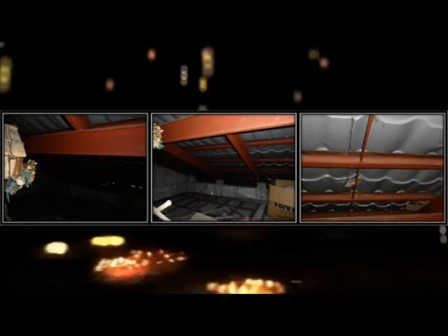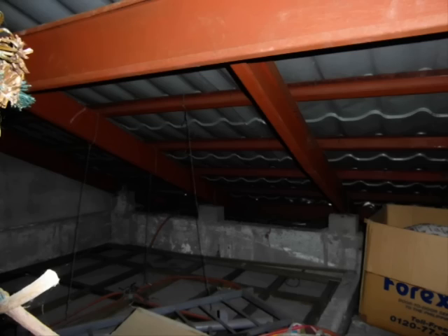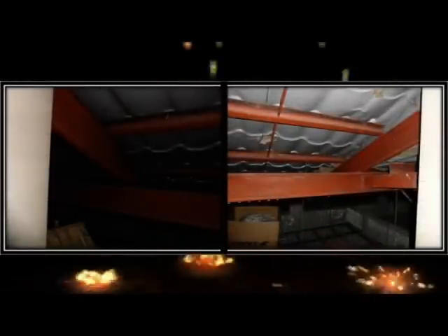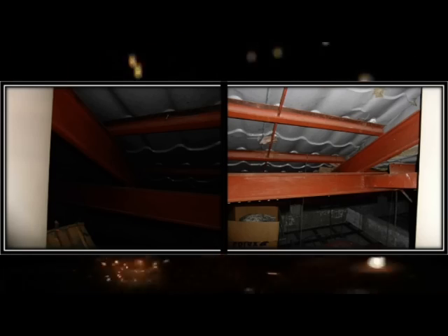For example, most roof trusses are conceived by engineers to ensure they meet roof load and building requirements. By using fabricated roof trusses, builders can significantly reduce their total construction time. Another key advantage to using trusses is that of cost. Roof trusses are generally made from 2x4 stock. This stock is significantly less expensive than the longer framing pieces used in conventional stick roof framing. In addition, trusses can usually be installed by less experienced carpenters, allowing builders to save on labor costs.